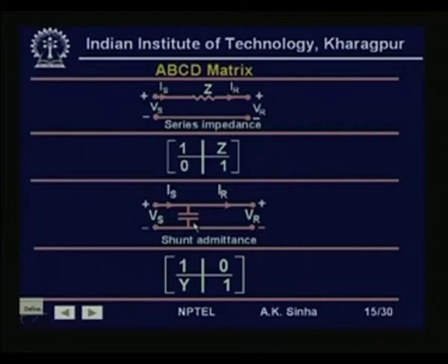to compensate for the reactive power drawn by the load. So, many times when the load, which is highly inductive, draws a large amount of reactive power, we need to compensate this reactive power by putting capacitance at the receiving end.